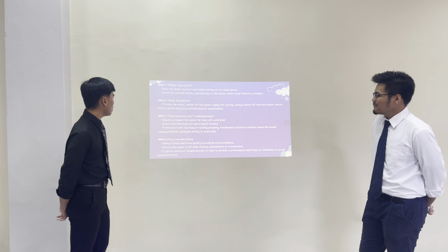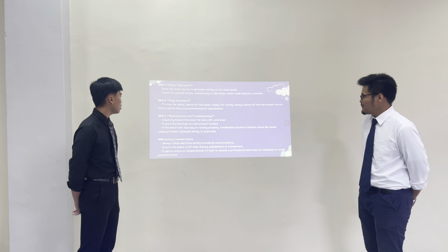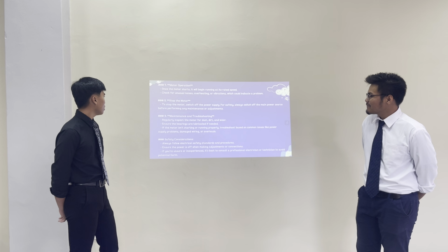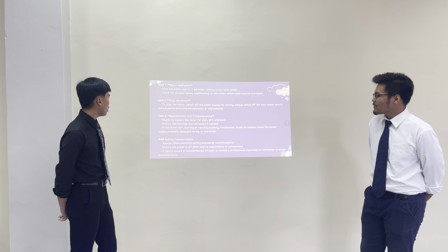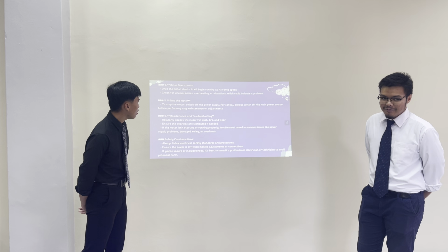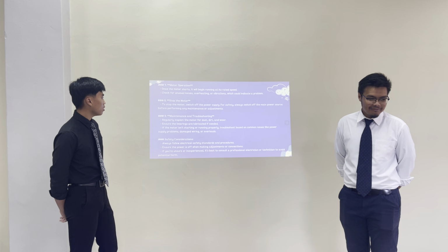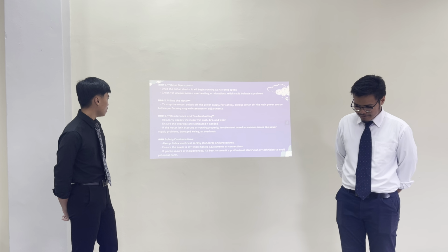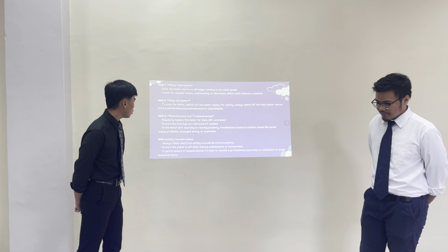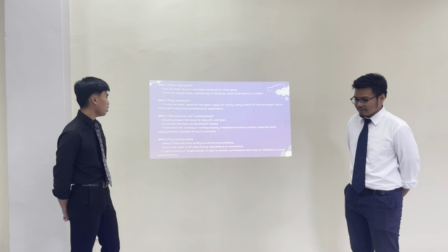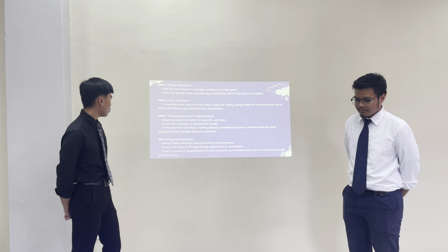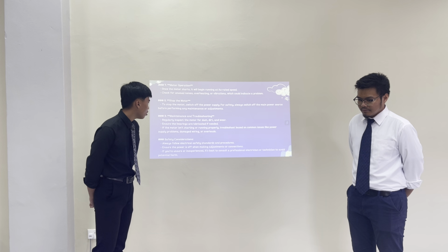7. Motor operation. Once the motor starts running, check for any loose parts, overheating, or vibration, and stop if there is a problem. 8. Stop the motor. To stop the motor, turn off the power supply. For safety, always turn off the main power source before performing any maintenance or adjustment.